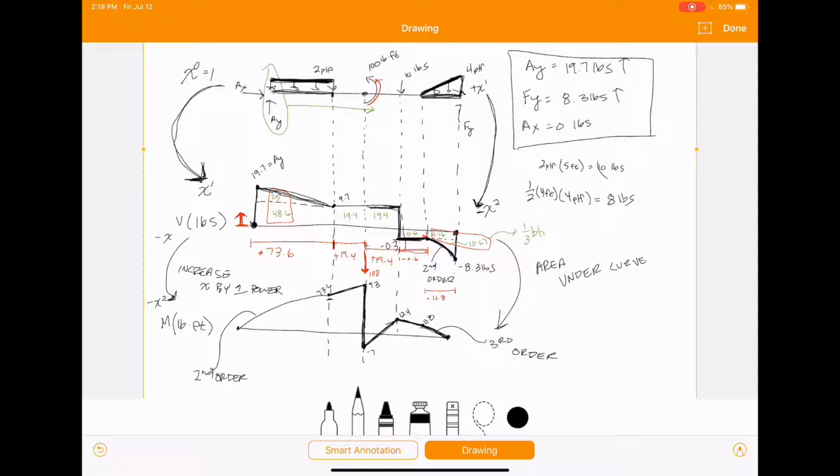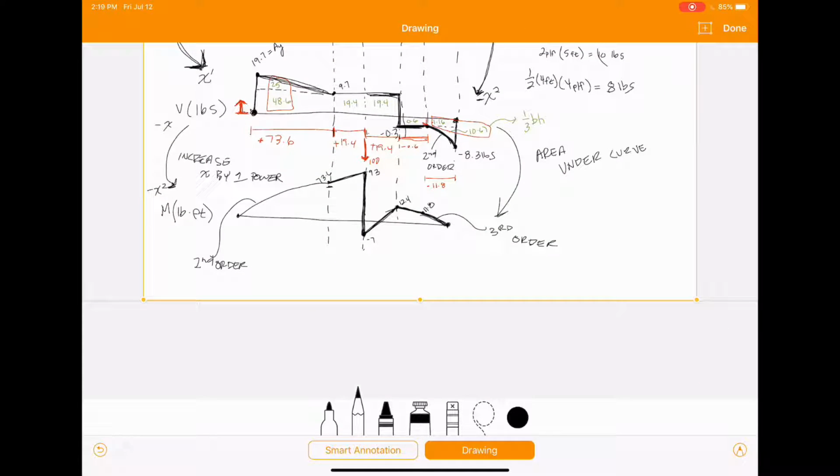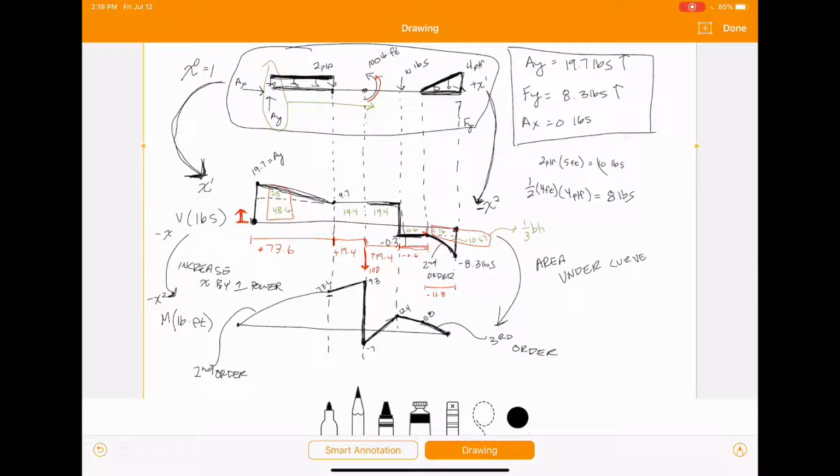And it's as simple as that. There's your shear moment diagram. There's really nothing else more to it. Really, you can just look at what's happening with your loading up here and translate that down into shear and moment. But of course, if you had a hard time following that, you're just not really understanding how you look at it and you get it, that's okay. You can just go ahead and cut the beam here, here, here, here, and here. Develop your equations, and then just graph those equations to get your shear and moment diagrams.